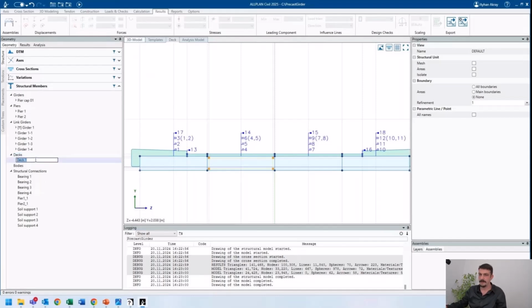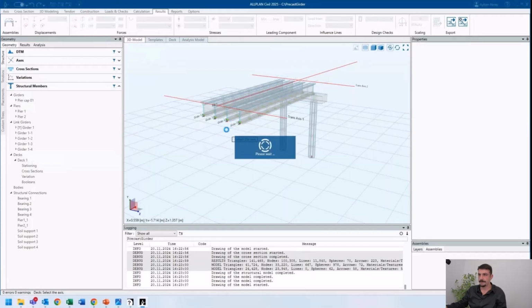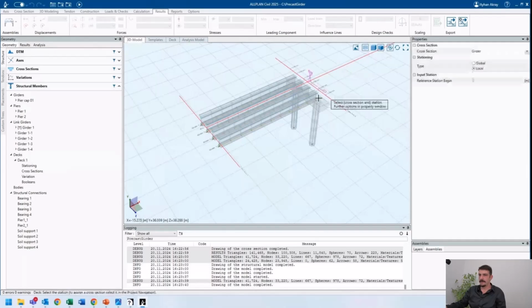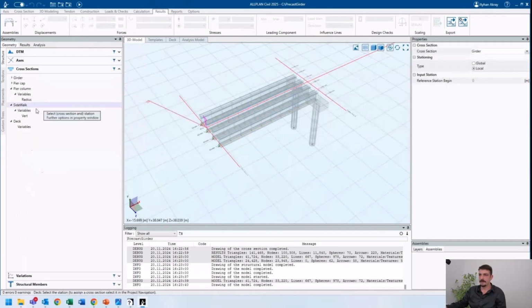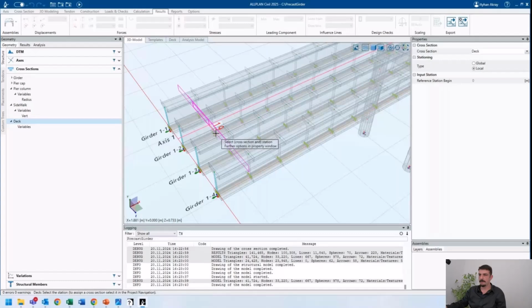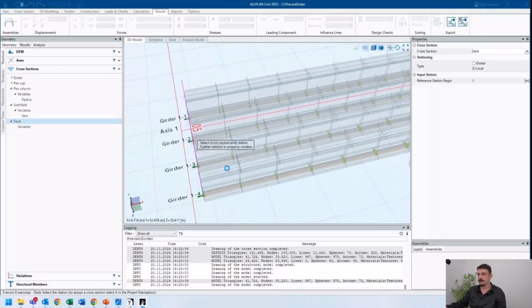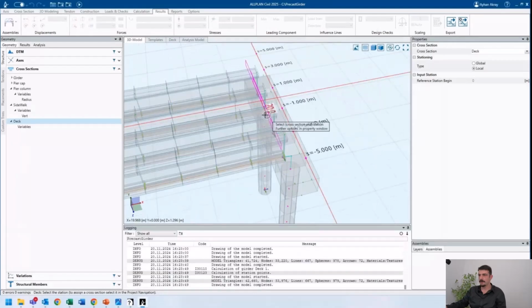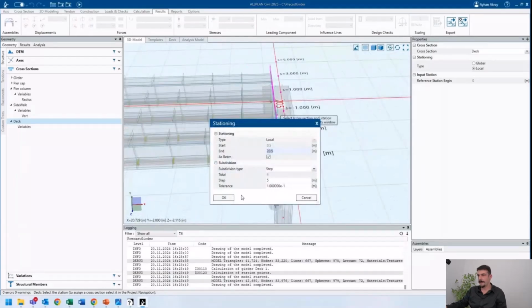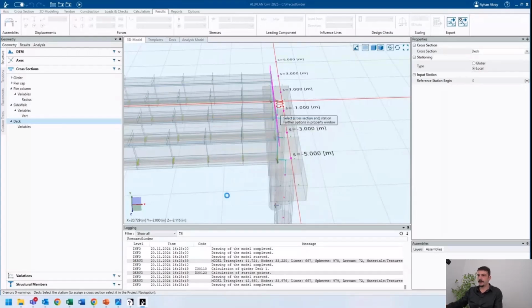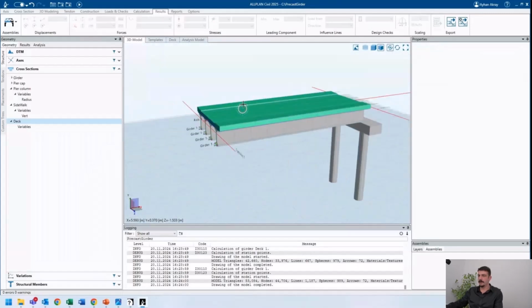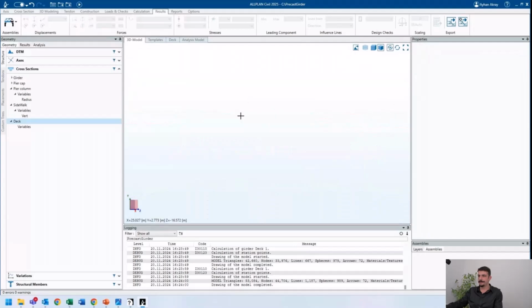So I will press enter. It will suggest me to select axis. Now I will switch to the deck cross section, and my first point would be 0.5 as the beginning of the precast girder, then last point to the 20.5, and total division of 10 meter maybe. And remember, blue color means there is no material in the system.